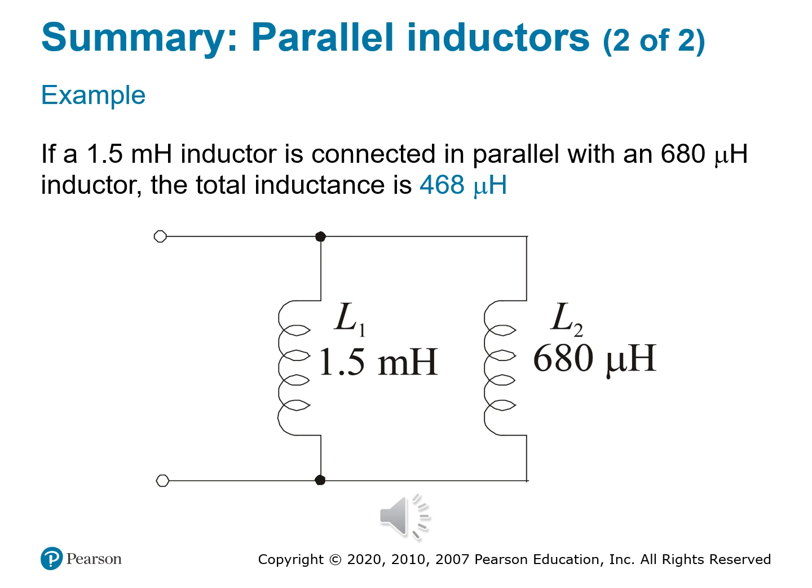Okay, I had two titles for this slide: parallel inductors, you do the math, or parallel inductors, let's do the math. You choose. Anyway, you can keep them both. So now that you've seen the theory behind inductors in parallel, let's work through a practical example because this is where it really sticks. So in this slide, you're given L1 is equal to 1.5 millihenries. L2 is equal to, again, 680 microhenries, and we convert that to millihenries. 680 microhenries would be 0.68 millihenries. Again, these inductors are connected in parallel, and we want to find the total inductance, L sub t.